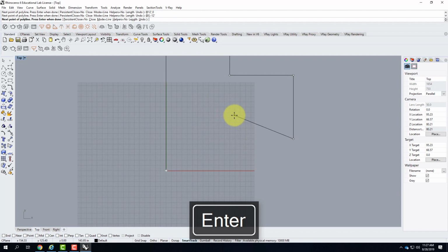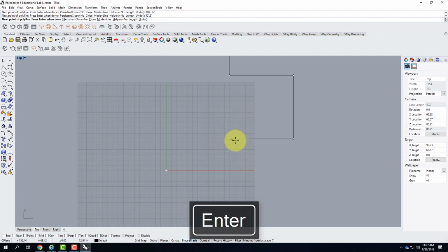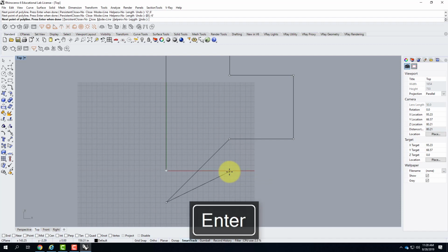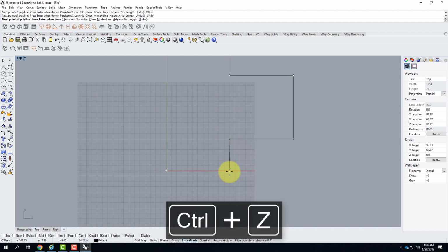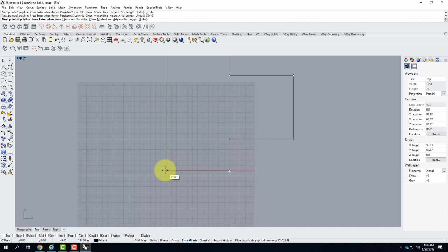Now the other thing about it is I can switch back and forth. So I could go back to absolute coordinates if I wanted. So this next point would be at 12 feet, comma, 6 feet. And that can get me to that point. This point down here could be at 0, comma, -6 feet. Oops. Helps if you actually type it in correctly, which I didn't. @ 0, comma, -6 feet, and there it is. And then I could finish off and snap right back to where I started.